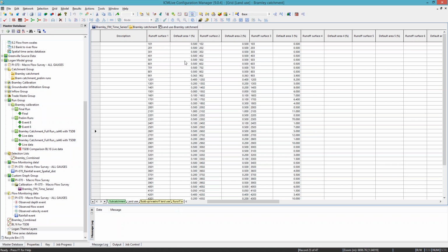I mentioned before, Australia has separate systems. So typically we see very small percentages that actually directly contribute back into the sewer system. For a combined sewer system, the percentage might be 80 or 90% or more. But for a separate system, we'd expect something in the order of 3 to 5% for an older system, or 10% for a really poorly performing system. For a newer system, the number could be as low as 0.1%.